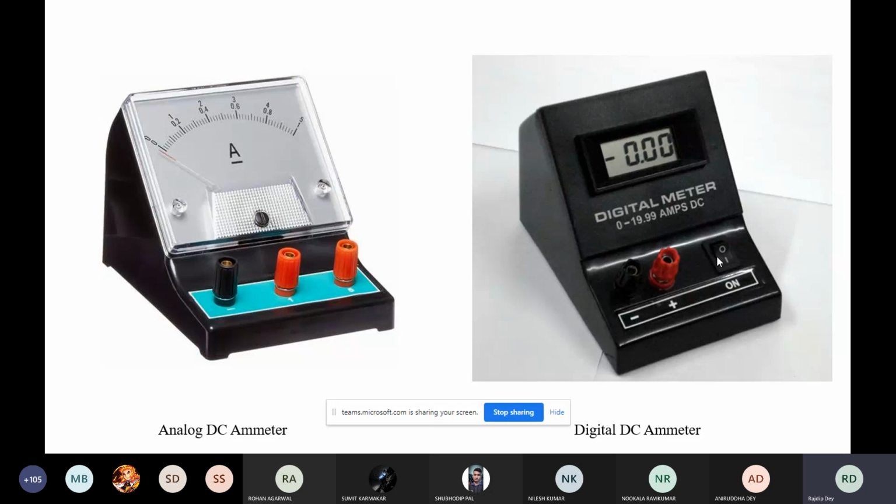So we'll understand that our current is very small, but it is not measurable by the 5 ampere range. So what we'll do then is change the connection from 5 ampere to 1 ampere and measure. Otherwise, if we just connect to 1 ampere and our current is more than 1 ampere, then this instrument will get destroyed because it is not connected to the 5 ampere.